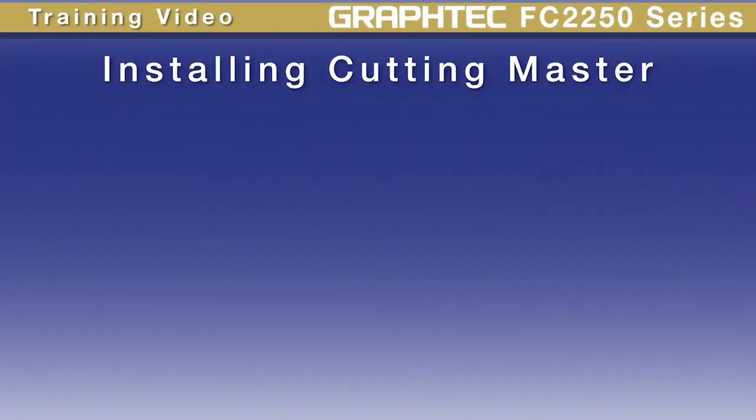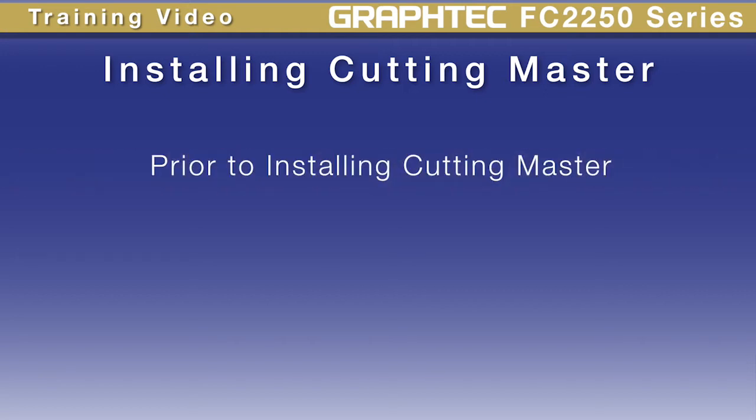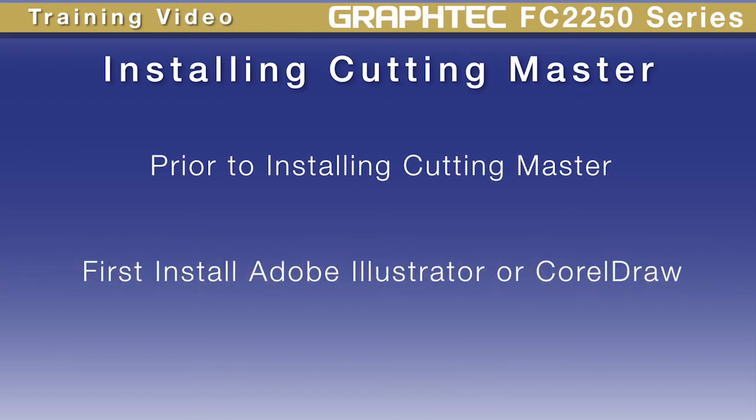Before installing the software, there are a couple of steps that must first be taken. When installing Cutting Master, it looks for either Adobe Illustrator or Corel Draw to install the plugin. So prior to installing Cutting Master 2, install the graphics application you plan to use, whether it is Adobe Illustrator or Corel Draw. The interesting thing about Cutting Master 2 is if both Adobe Illustrator and Corel Draw are on your system, or different versions of the same application, it installs Cutting Master 2 in every compatible version.